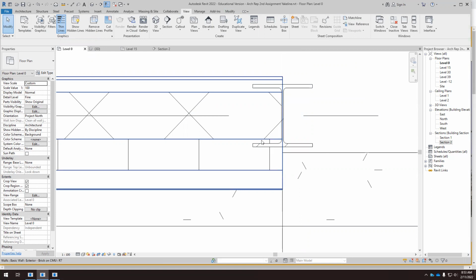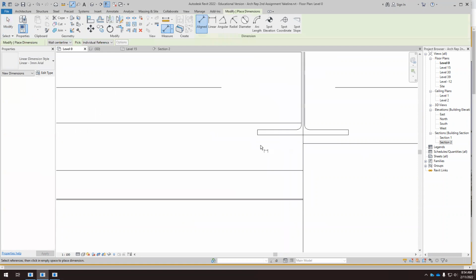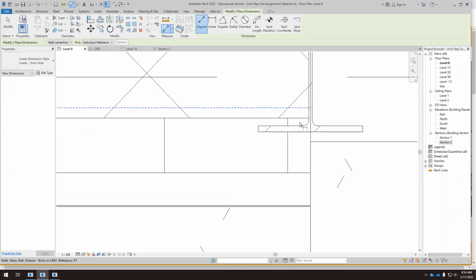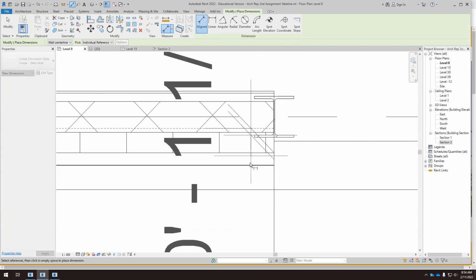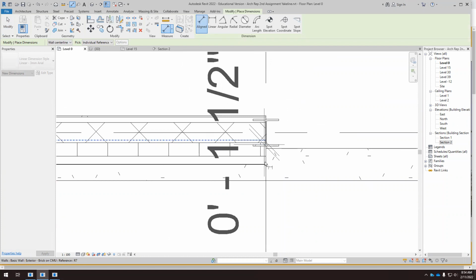We still have this problem, so what I'm going to do is create an air layer. I'm going to move the thermal insulation outwards. How much? This distance. I can find out this distance: I can go to annotate, align, from this point. Yeah, I think 1 inch would be enough.